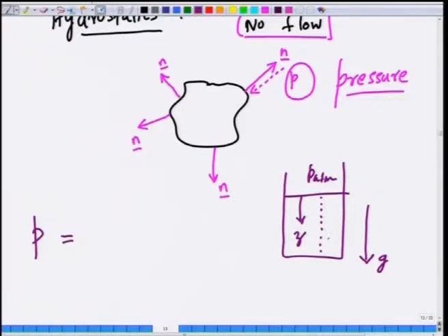The pressure has to increase so as to balance the body force that acts on a given parcel of fluid. For a volume element, there is a net force acting downwards, which is the mass of this element times gravity. So, the pressure has to be larger here to support this force in order for the fluid to be under static conditions. That gives rise to this famous pressure variation under static conditions.